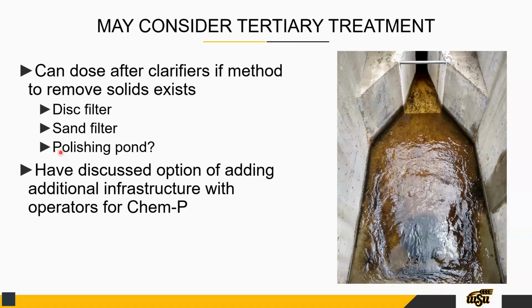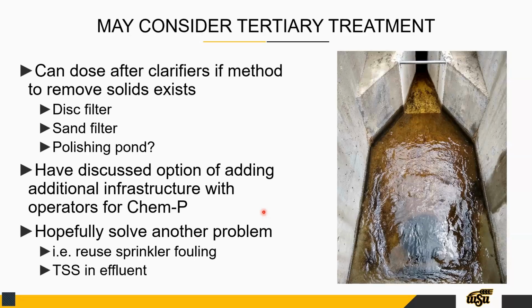I think that might be flirting with disaster because you'd have a lot of solids settling in it, and then you lose pond capacity. Possibly to see release of phosphorus there as well. So this is a discussion we have with operators sometimes about, is there a benefit besides phosphorus for adding tertiary treatment? So, you may not have the best total suspended solids performance, which would be a good reason to have it, or you may have reuse.